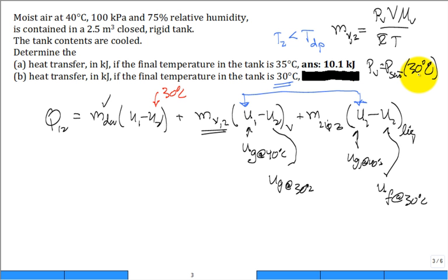All right. How do I get now the mass that's vapor? How do I get the mass that's liquid at the end of the cooling process? Conservation of mass. You already calculated from part A what started in the vapor state, and you subtract out what ends in the vapor state. The difference is the liquid. So maybe I should do that.